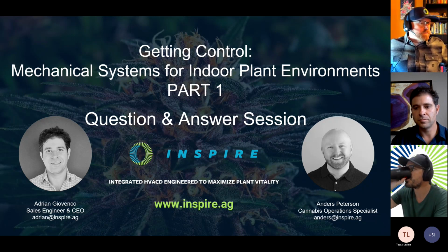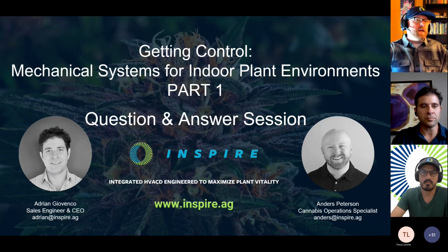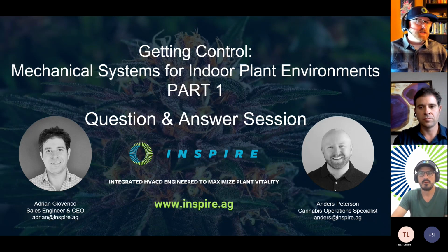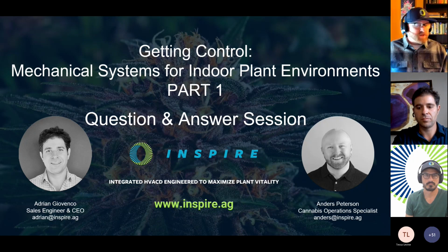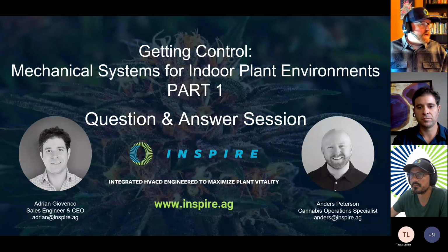From a mechanical system perspective, it can be a pro because you are easing that load in and allowing the unit to catch up a little bit easier in terms of its capacity and its speed to hit set point. However, from a plant perspective, or an optimizing cultivation perspective, every time you dim your lights, you're sacrificing the total daily photon uptake of your canopy, or what's called the DLI. And so every time you sacrifice light, you sacrifice yield essentially by a little bit every time.